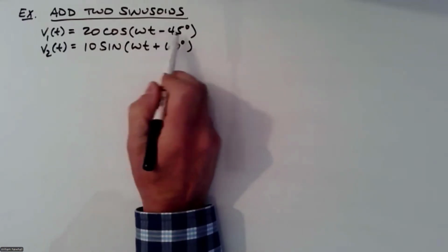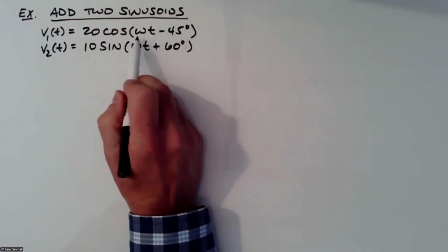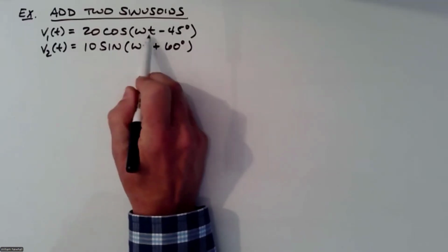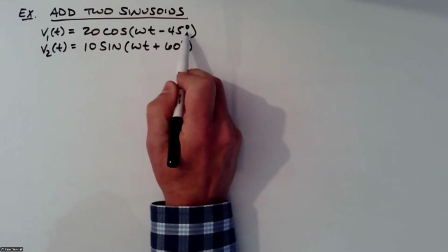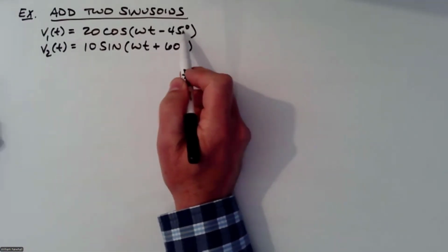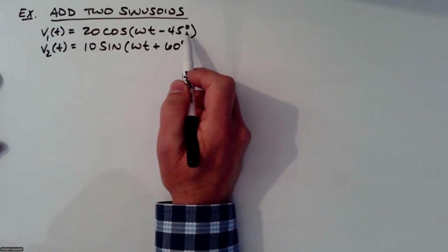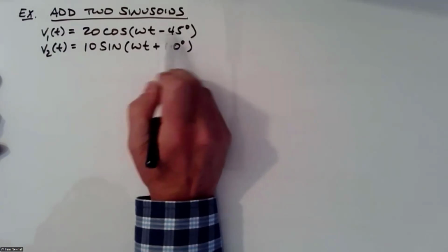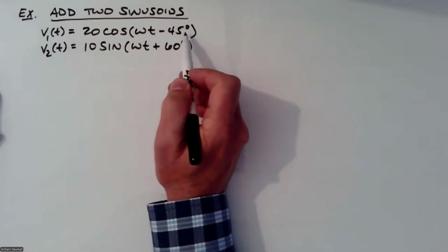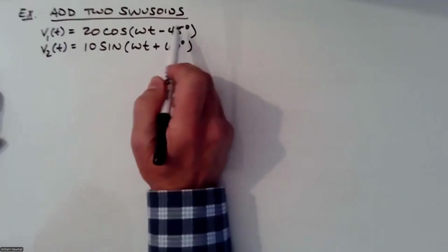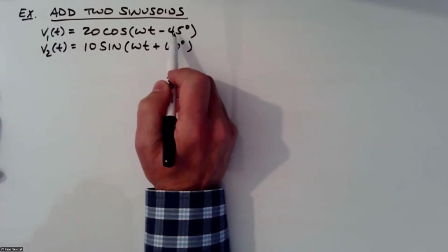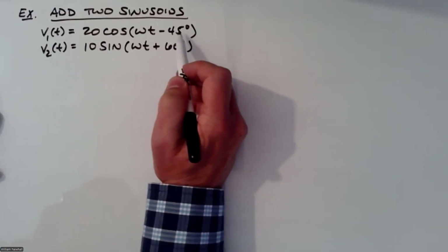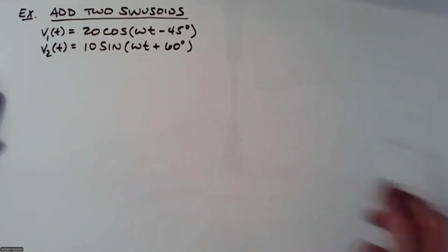One rule is that I'm mixing units. I have omega t, that's radians per second times seconds, that's going to be radians. And I'm subtracting degrees. You cannot do that when you're actually doing calculations. But we break this rule all the time just to be able to visualize where this phasor is or what the phase of that cosine is, right? Because you could probably visualize the angle 45 degrees, right? If I say visualize 45 degrees or 30 degrees or 60 degrees, you could probably do it.